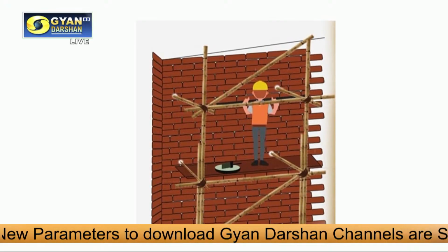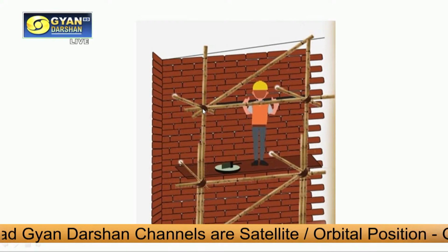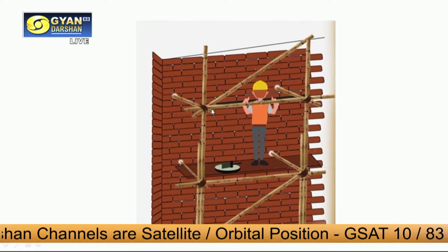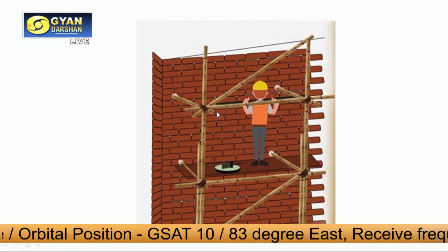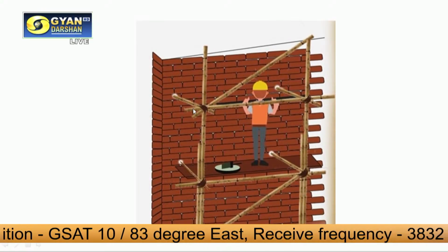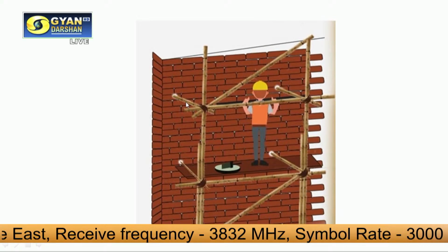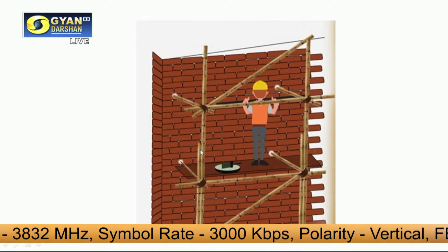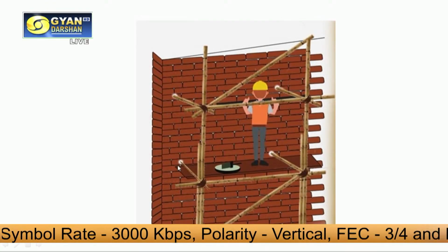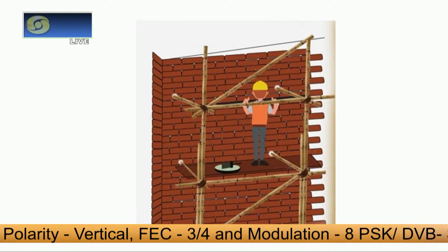One end is tied here with a coupler to the ledger and the upright, and the other end is going into the wall. So these horizontal members at 90 degrees to the wall are the putlogs. Here is a platform where the worker is standing and working. So this is how it looks.